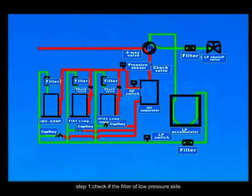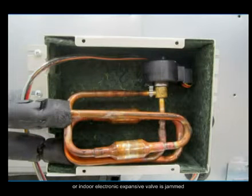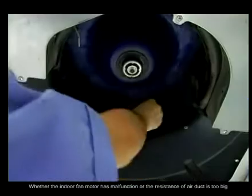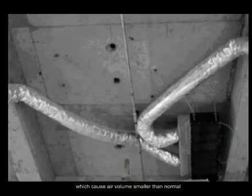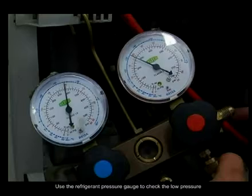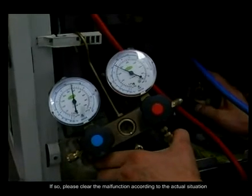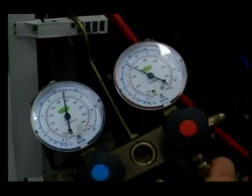Step 1. Check if the filter of low pressure side or indoor electronic expansion valve is jammed. Check if the indoor evaporator or filter becomes dirty and causes heat exchange badly. Whether the indoor fan motor has malfunctioned or the resistance of the air duct is too big, which causes air volume smaller than normal. Use the refrigerant pressure gauge to check the low pressure. If the pressure is too low, the above situation can exist. If so, please clear the malfunction according to the actual situation. If not, please go to the next step.